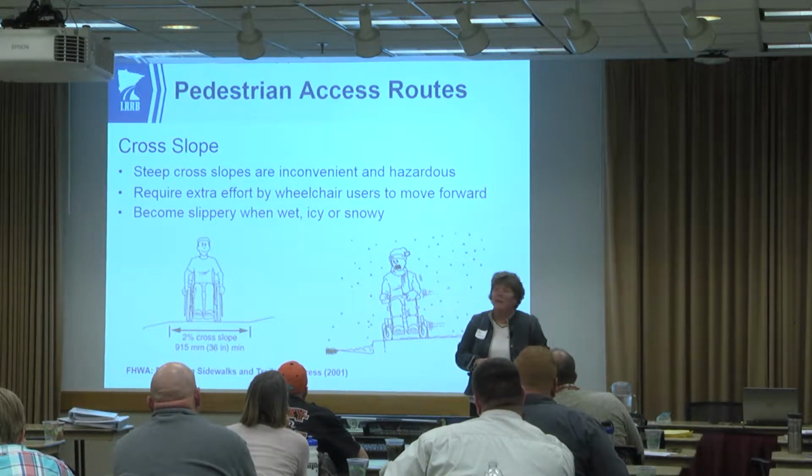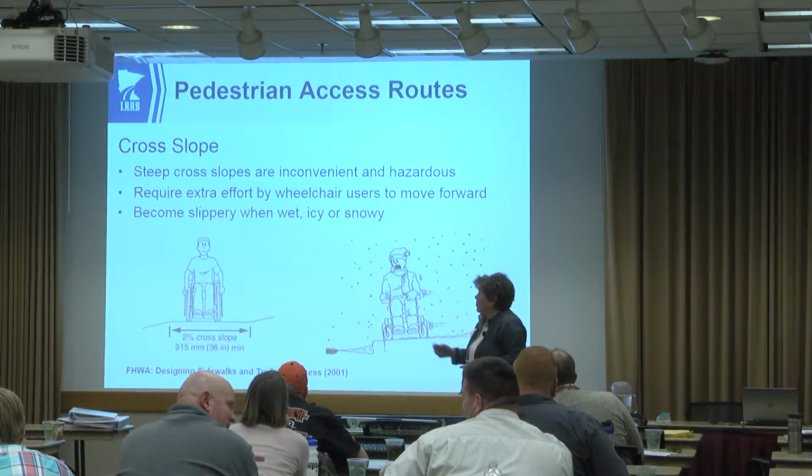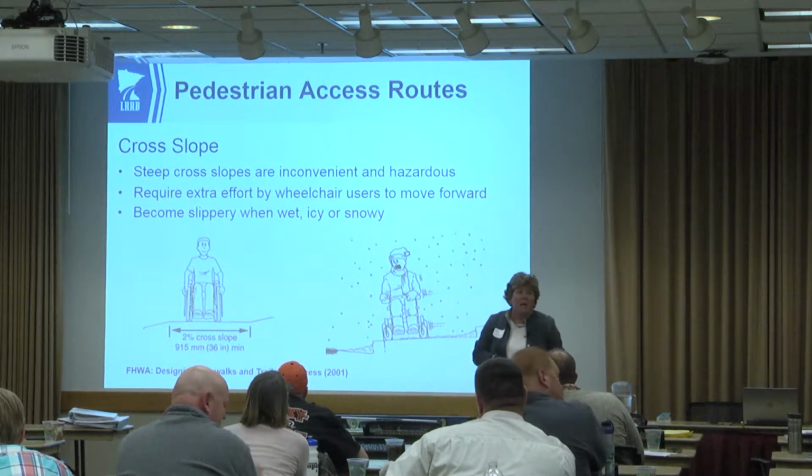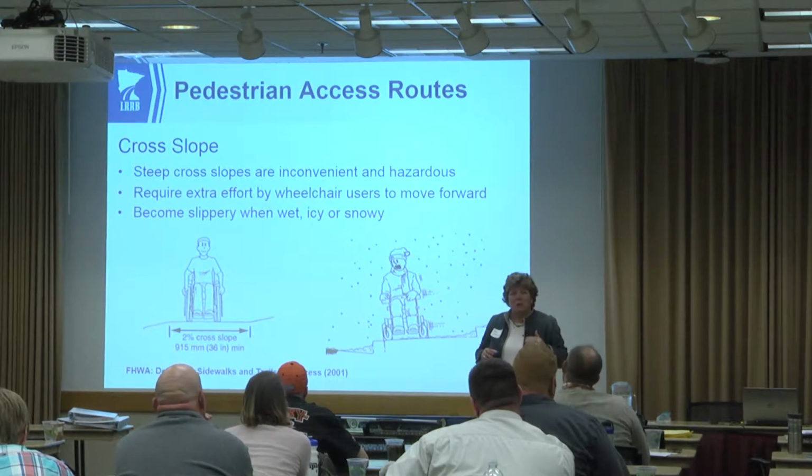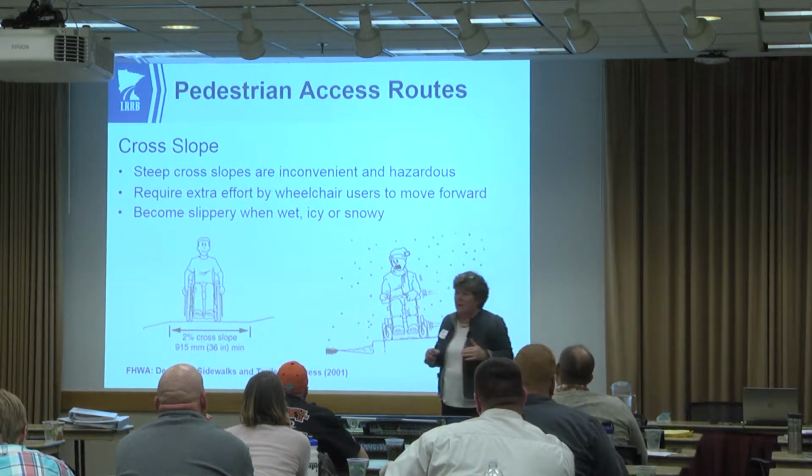It was treacherous, and I kind of wanted to survey it and see what it was, but I didn't have my 4-foot level with me. But cross slope can be a really difficult thing. So we try to maintain a pretty flat cross slope. Now remember, that's a 2% max. It doesn't mean that you lay that every time.